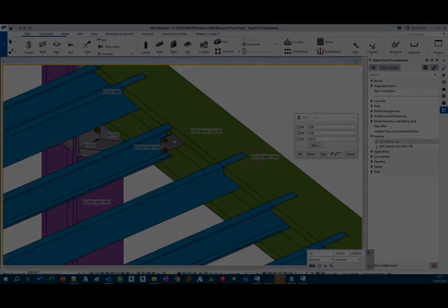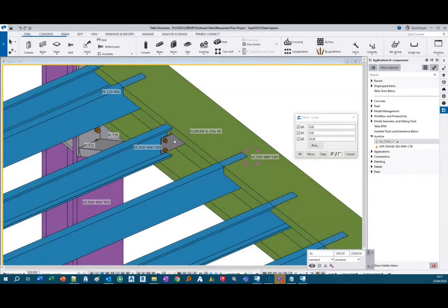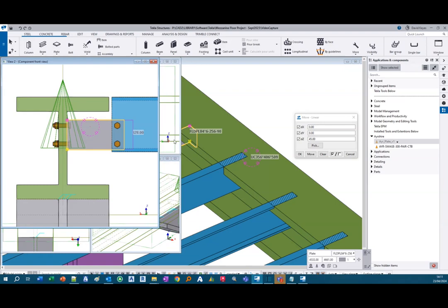Some floors have UC primary beams with flange widths that are too wide for standard cleats. There are also times when the flange root radius clashes with the standard brackets. For these conditions, Ayrshire can design and make custom cleats and supply beams with offset punching. Please contact sales@ayrshire.co.uk for further information.